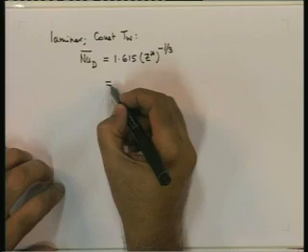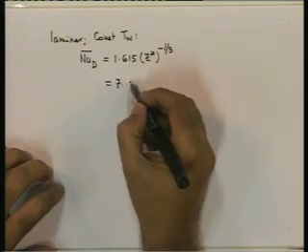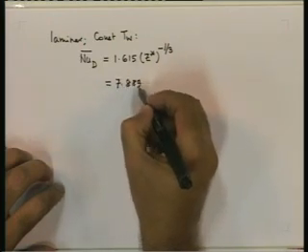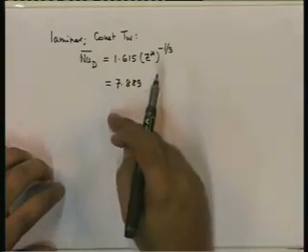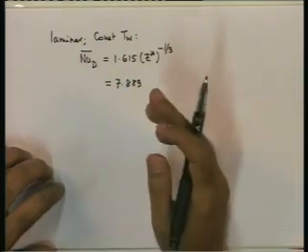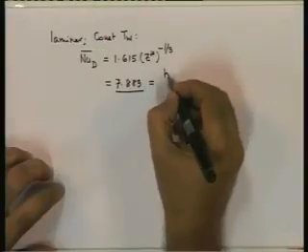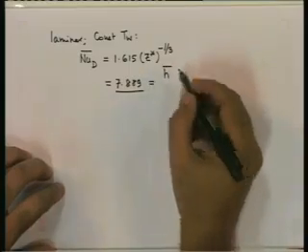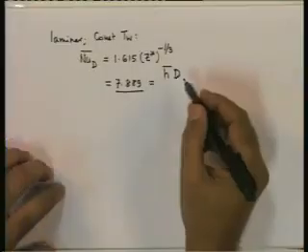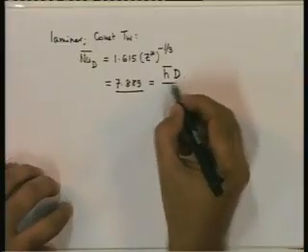This turns out to be 7.889. If it were fully developed, this would be 3.634. So this is significantly higher than that. Not quite twice, but definitely more. Why? More than twice. Now this Nusselt number is nothing but the mean heat transfer coefficient or the average heat transfer coefficient over that length multiplied by D divided by K.